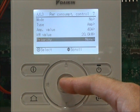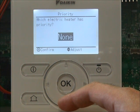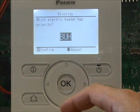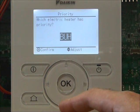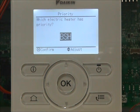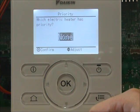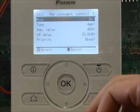We go down to priority, click on OK. Which electric heater has priority? None of them. So if none of them have priority, the booster heater and the backup heater can operate together if required. If the backup heater has priority, the backup heater has priority over the booster heater. And if the BSH, the booster heater, has priority, it means it's basically an electrical interlock, so they can't operate together. If you're not limited for power supply, then set that to none. Okay, so that's power consumption control complete.